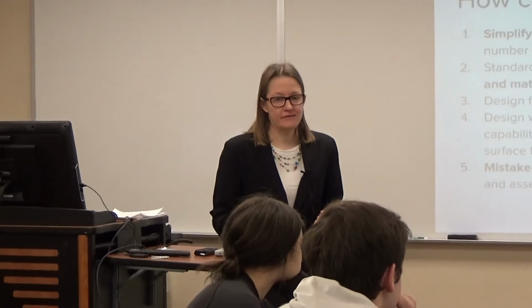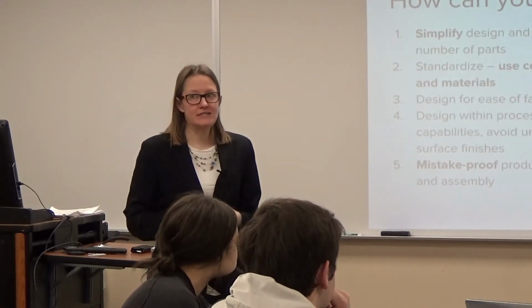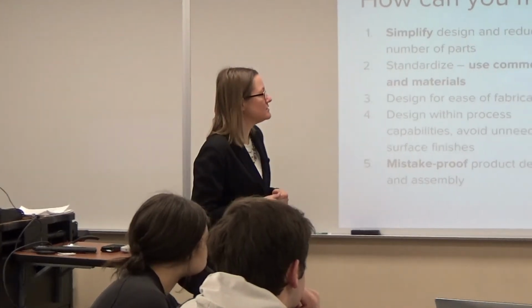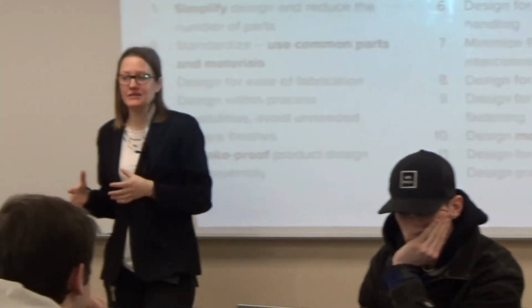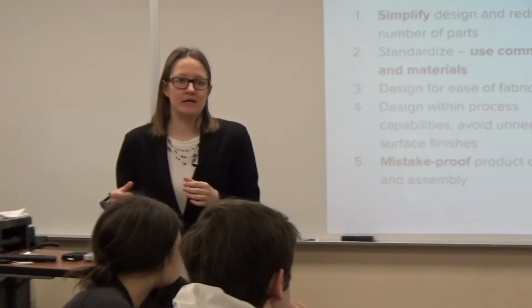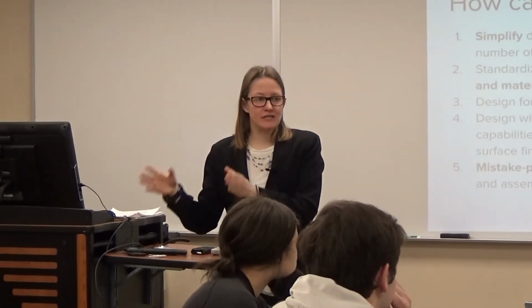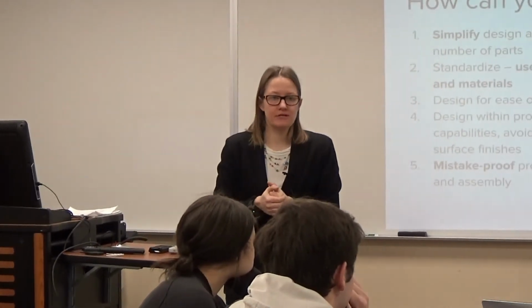Think about making a mistake-proof product or design. So how might it fail, right? How might a user make it fail? That is actually DFMEA, and we'll talk about that a little bit later, but something to consider. Then you could think about things like ease of assembly or trying to make things modular. Like, if our end product is something we actually build, could we manufacture it in 3 different maybe plants and then put it together at the end and assemble it?